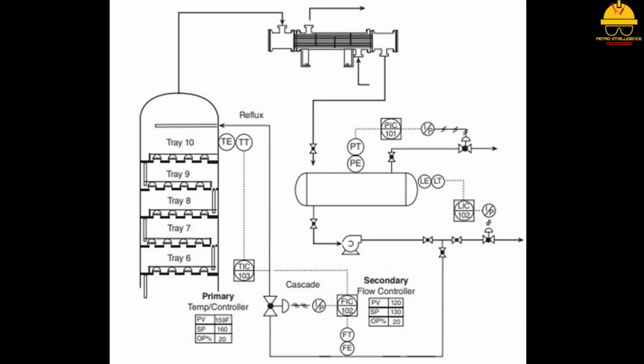A cascaded control loop has one primary or master controller and one secondary or slave controller. The master controller is wired to the secondary controller and has the ability to override the initial or original set point. During operation, the secondary controller operates with all 5 elements of the control system. The master controller has 1. a primary element, 2. a transmitter, and 3. a master controller electrically connected to the other control loop. This picture shows how a typical cascaded control loop looks.